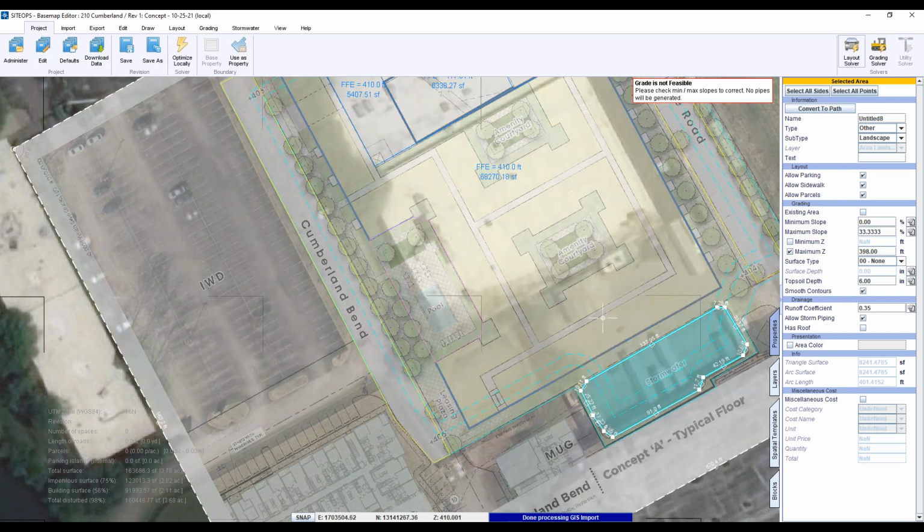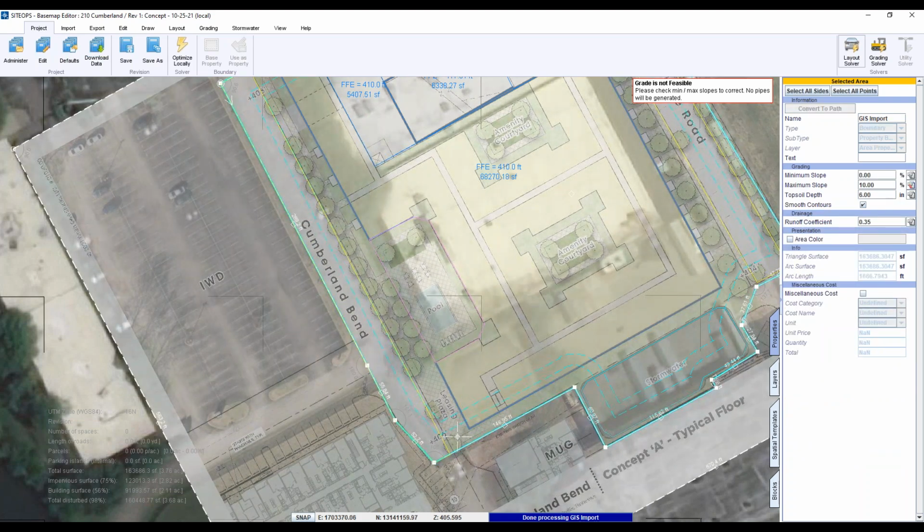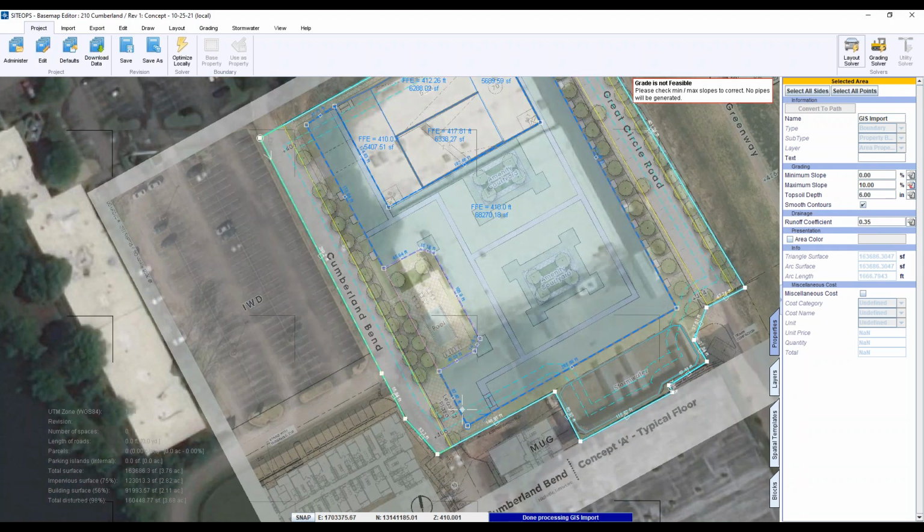A lot of this one is forced elevation because that's just what we have here. Then to get it to grade properly on an urban site, I also constrained the max slope to 10%, which worked well. Sometimes if the site has too much topography, that might not work, but generally on urban sites I like to constrain it because you're so full of sidewalks and things around it that you're not going to see any really aggressive grading.